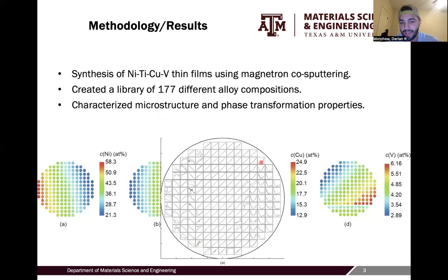On the right-hand side of the wafer, which is where the shape memory effect was actually visualized, you can see these U shapes that are reversible with some hysteresis, which are typically identified as the shape memory effect, which is what these authors were looking at for this quaternary system. They also characterized the microstructure, and they did this by using WDS, or wavelength dispersive spectroscopy. This confirmed and identified the compositions at each region. All of the dots you see in this image in the back, they used WDS to find those.